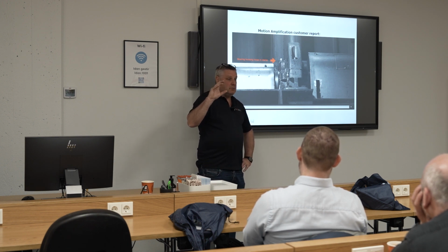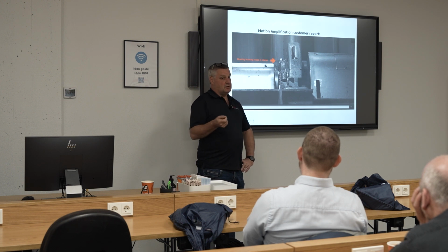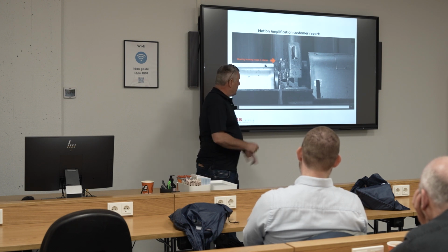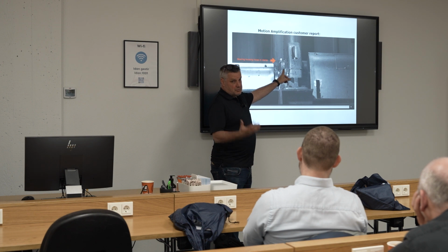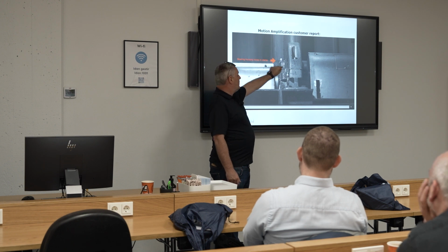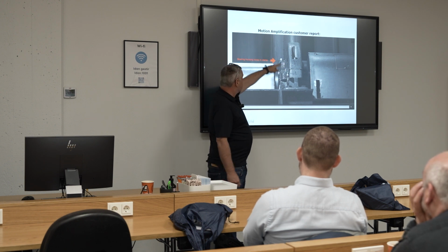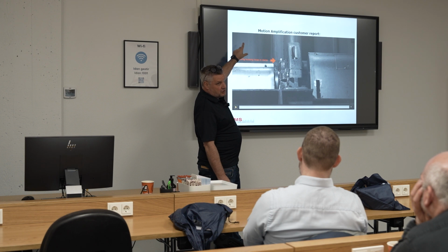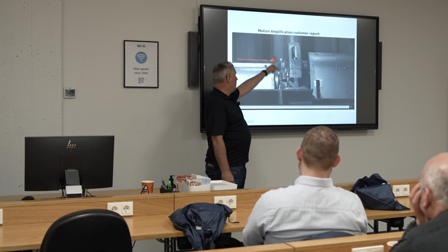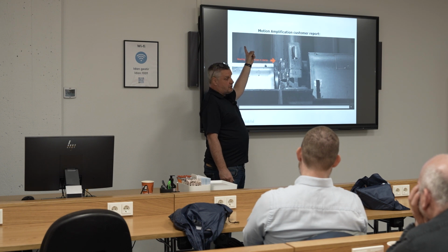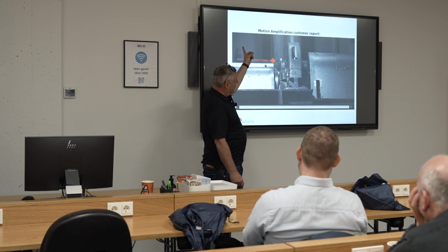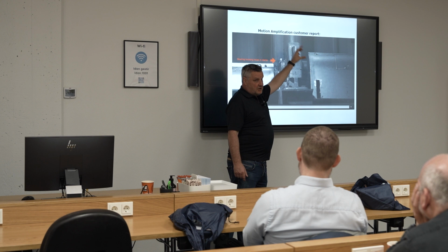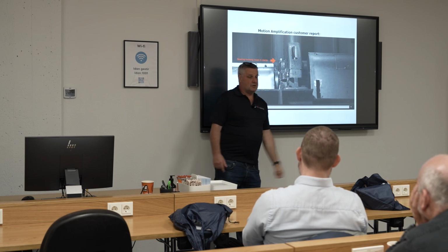And then ultimately, we would take a vibration signature. This is how we do it. We'll take a vibration signature of that with our instrument, and it'll read 10 millimeters per second. Then we will put an ROI on the screen, do our velocity spectrum, and it should read similar. So it's always going to read similar with the spectrum, but with the amplification, we can make it look worse than what it is.